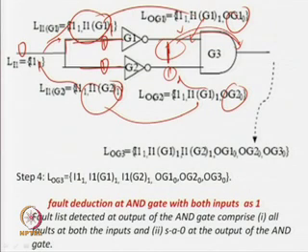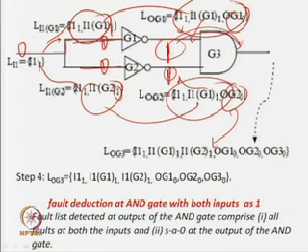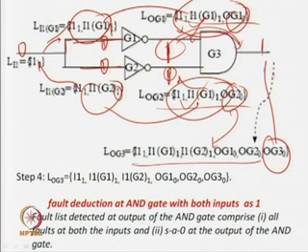In this case both the signal values are 1 1, because of the random pattern 0. So whatever the list over here and whatever the list over here, the whole thing will come over here. If you study this list and this list, the whole list takes care of this one and this one, because we are applying 1 1. And with 1 1, the output signal value is 1, so you can also detect a stuck-at-0 fault at this net. So these are the fault lists for this random pattern 0. You can detect any number of faults.